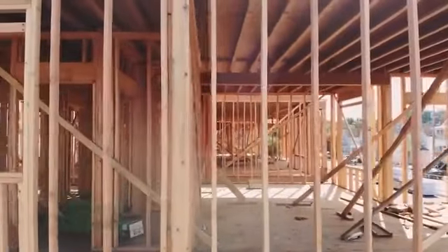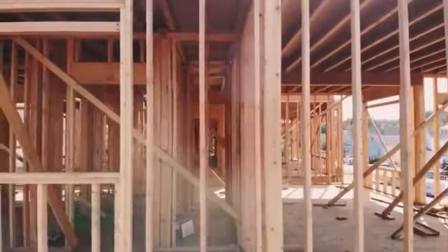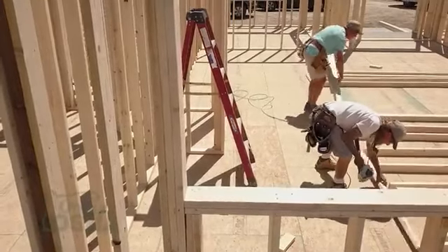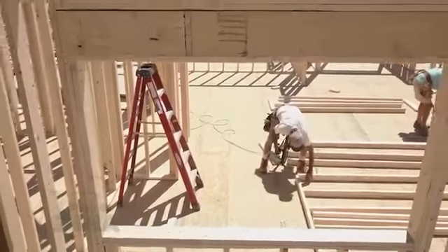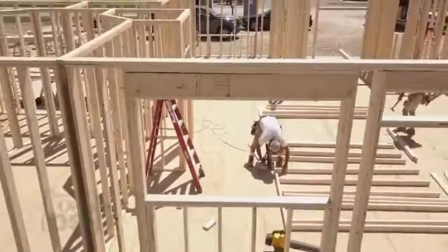As we're framing, we don't have structure that's able to hold 5,000 pounds or 1,800 pounds. We don't have a lot of fall clearance below the people who are working up there framing. So when we look at that, active fall protection is probably not the most effective means of providing protection for those workers. We should be looking at what we can do on the ground. How much of this can we build on the ground at that lower level and stand up complete? Can we scaffold around it?